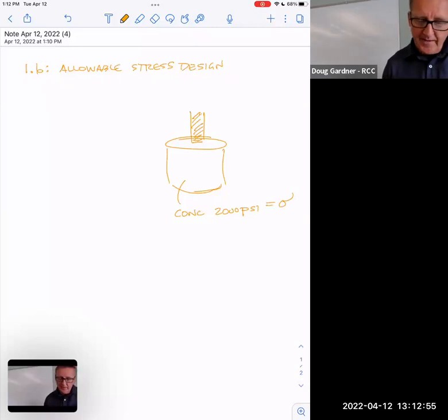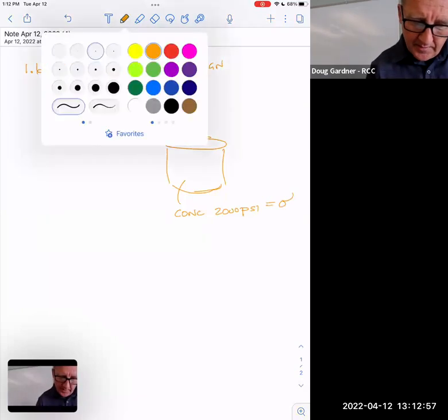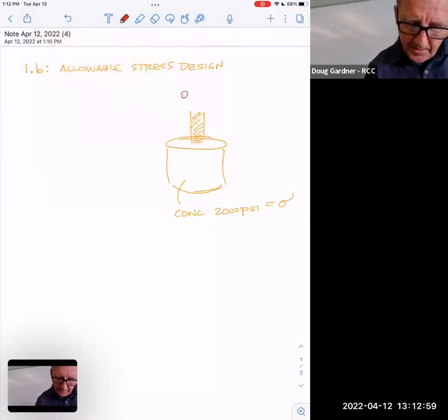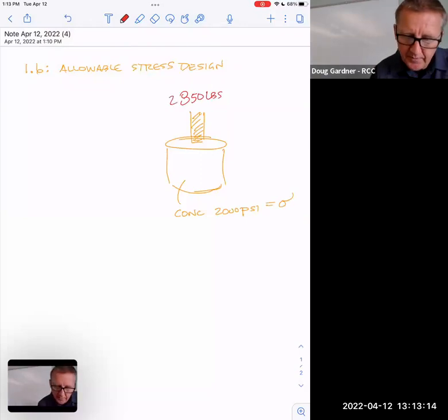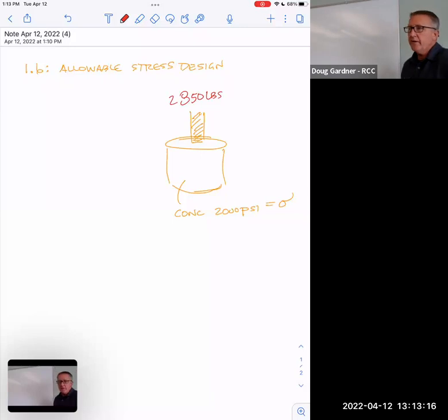Does it make sense that if I put, say, 850 pounds up here, is that going to break that concrete? And the answer is you don't know. You can't say yes or no yet. What if I said 2,850? Is that going to break that concrete? No, you don't know because you don't know how many inches you put on it. Does that make sense? You got to know the size of the post.